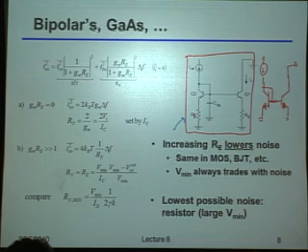So you'd be left with only the noise from the resistance itself. In other words, if I allowed the voltage drop to increase, and you looked at the noise current as a function of that source resistance, it would monotonically go down. It would go to essentially just 1 over RE in the limit, in terms of the current proportionality. Does that make sense?